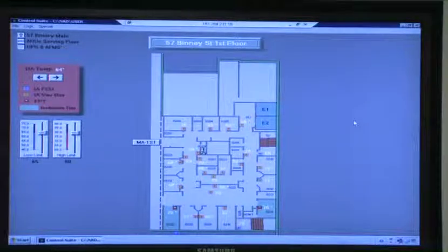So if they decide to prop this small one open, it also will stop the alarm from coming in. You've got to understand, pressure monitoring through sectors and all that stuff is only as good as the box, the tight box that's formed to have that pressure relationship to its outside adjacent spaces. Meaning, you can't have a pressure sensor in this room and have that door wide open. It won't maintain pressure. You have to close it, have a sealed box, then you monitor it.